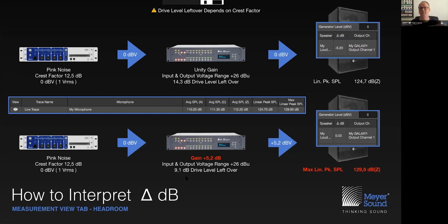It is at this point that the scales start to tip. If we exceed this value, then we enter the domain where the loudspeaker will no longer be running in its linear range of operation. Then we will start to see the onset of compression and/or distortion. But up to this point, the loudspeaker is perfectly within its linear range. If you would like to know more about the stop conditions that we use to determine the max SPL of a loudspeaker, be sure to visit mnoise.org, where we have a written procedure that explains in great detail which stop conditions we use to determine the maximum level of a loudspeaker in such a way that it's still ensured that it's within its linear range of operation.